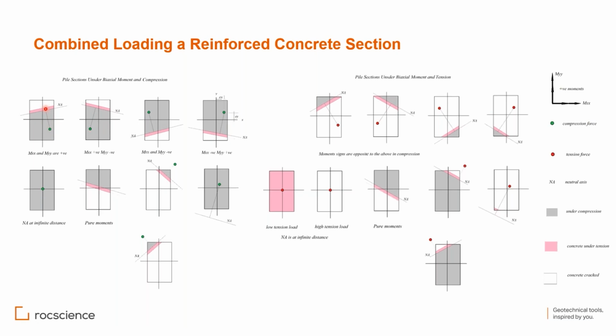So if you want to add the tension to your stress-strain curves, you need to use a stress-strain model that has tension. For example, the Whitney block of ACI does not include the tension. So the ACI code assumes that the cracked part of the concrete does not count for the tension resistance.